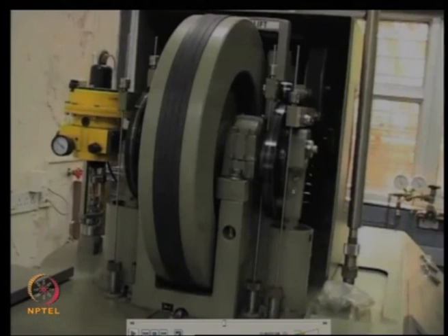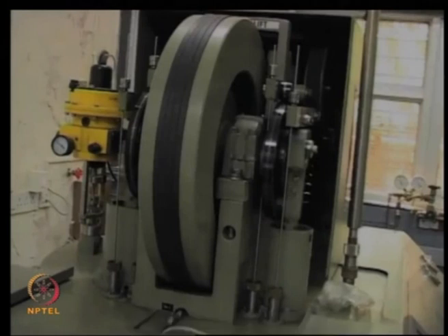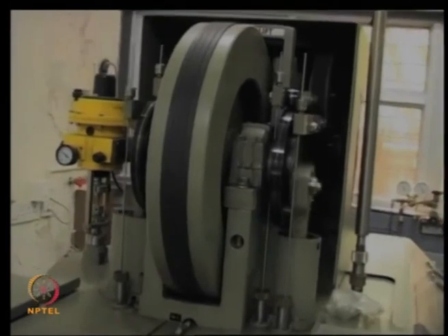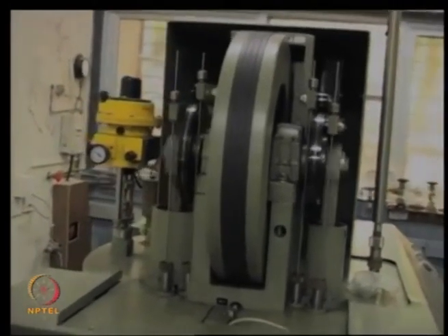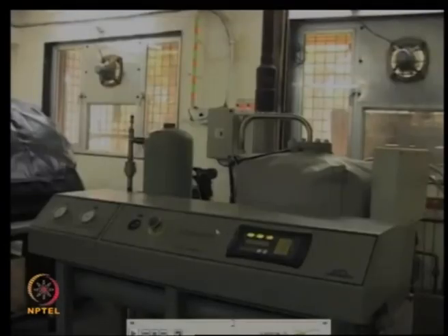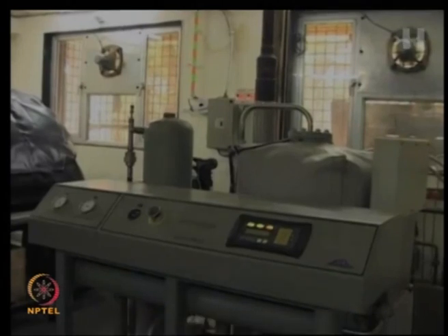and this expansion engine may be moving at 250 RPM, 300 RPM, and as the gas gets cooler and cooler, the gas becomes denser and denser, and in that case the RPM of this will be as low as around 60 RPM. So, that feedback control loop will be there, and depending on the temperatures inside, the RPM of this machine will change. All right. So, you can see these two expansion engines which are moving right now here. So, essentially what you have is a heat exchanger and the expansion engines.